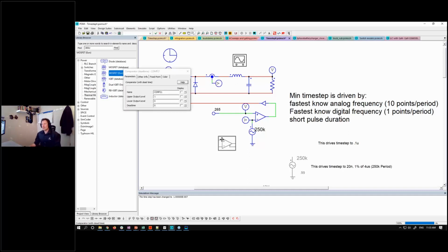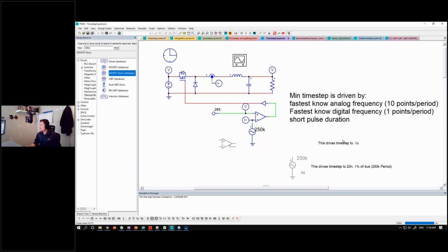One thing that I see people doing quite a bit is they start adding in dead time way too early. You don't need it to do a control loop simulation. Again, it's about divide and conquer. What's the point of the simulation? Do I need to have a really small time step for it, or a really big time step for it? Do I need to look at things that occur over long time periods and then make decisions based around that? Okay, back to my slide.